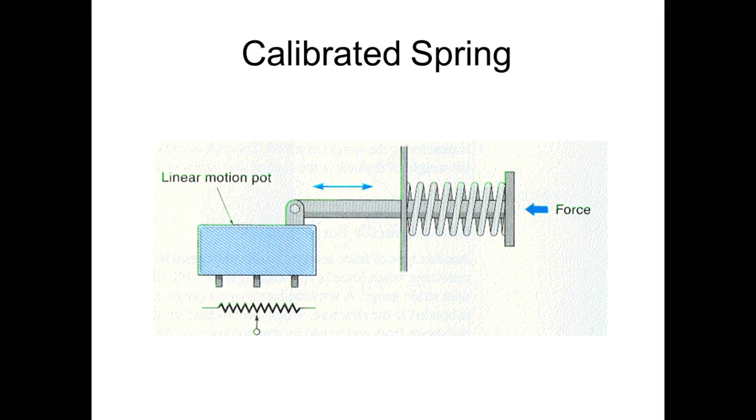So what they've done is they've taken a mechanical, nothing electrical. This thing does not vary its resistance. This does not vary a voltage. All this thing does is when we push in, it provides an opposite force. And if you ever did a spring, the further you push it in, the harder it is to push, right? You understand? So as soon as the force pushing back on the spring matches the force pushing over here, this sucker's going to stop. But what they got is they're coming over here making this thing move a linear potentiometer.